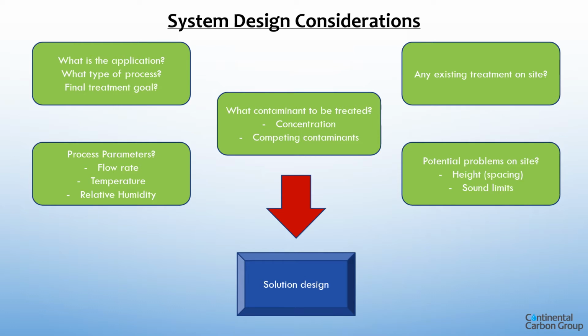Another potential problems which could be encountered: height, sound limits, process parameters, what is the flow rate of the application, what is the temperature, and if it's an air application then relative humidity. These are the kind of questions which need to be asked and answered before we can give you a comprehensive solution design.